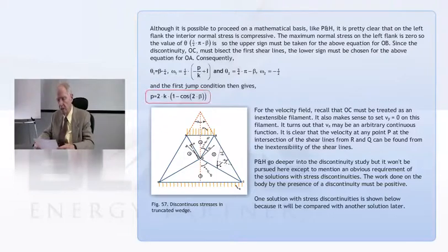You can use those regions of constant state to figure out what the pressures are everywhere else. And if you set the velocity along the discontinuity to 0, then the x velocity along the discontinuity, which is vertical in that picture, is just any old function of y.